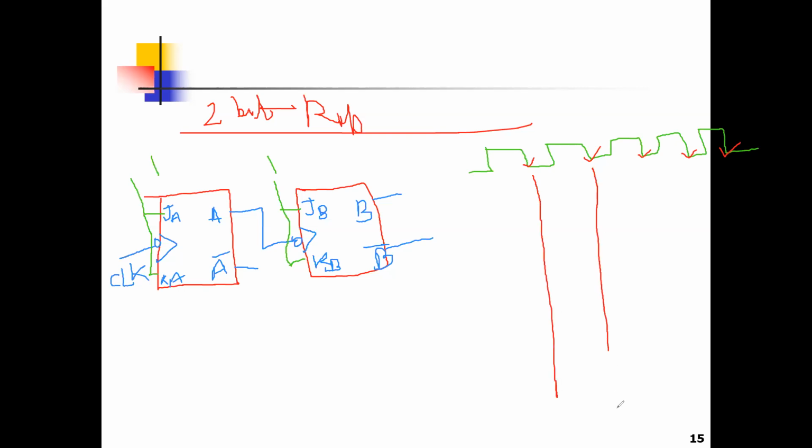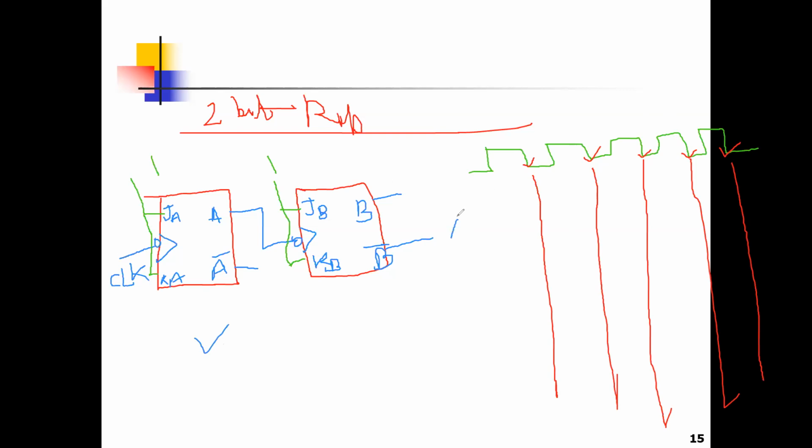Okay, now let's start. What will happen here? So first I will draw the A result. What is the waveform for the A, first flip-flop? So let's start to draw. If I want to draw the waveform for the first flip-flop A, the clock is negative. Before the clock, because this area is before the clock, the value will be 0.